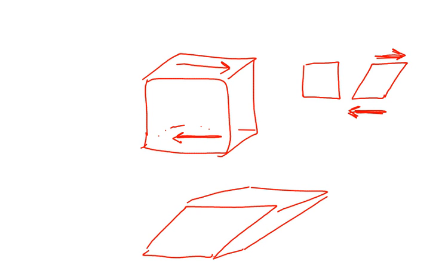So let's make that distinction clear. A normal stress causes elongation or shortening of your part. A shear stress causes a change in right angles. You start off with a square here, with 4 right angles, and after you apply a shear stress, you no longer have right angles. These 2 angles become obtuse, these 2 become acute. So that's how you tell when you have shearing in your part: right angles no longer stay perpendicular.